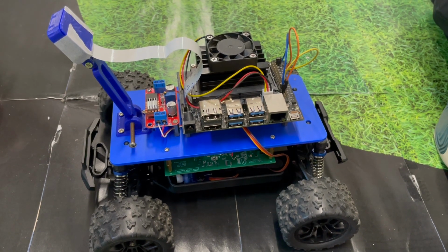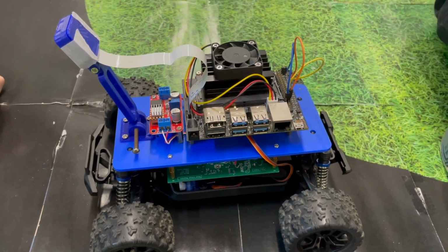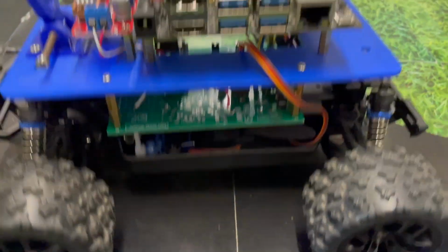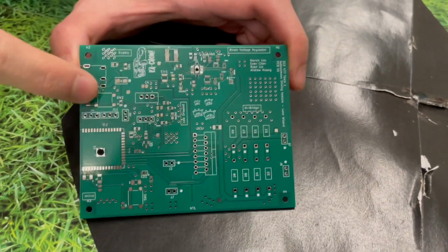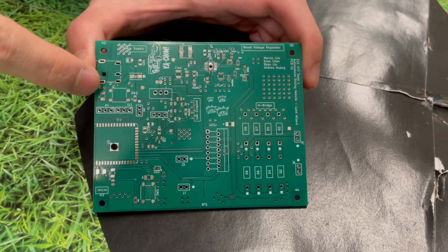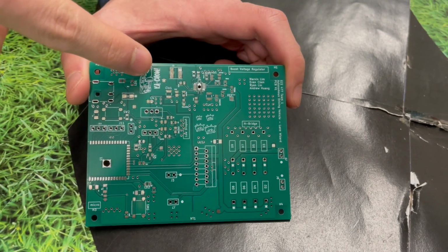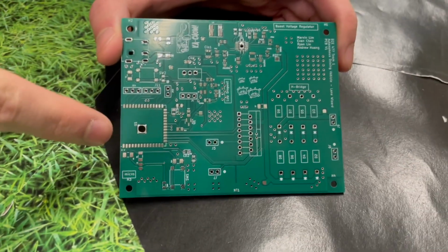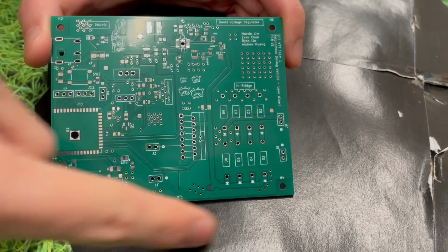First, let's take a look at the car itself. The major components of our car are the PCB, Jetson Nano, and camera. The PCB has a few functionalities: a barrel jack that takes a 5-volt input, a boost voltage regulator that converts 5-volt to 8-volt, a microcontroller that generates a PWM signal, and an H-bridge that uses the PWM signal to control